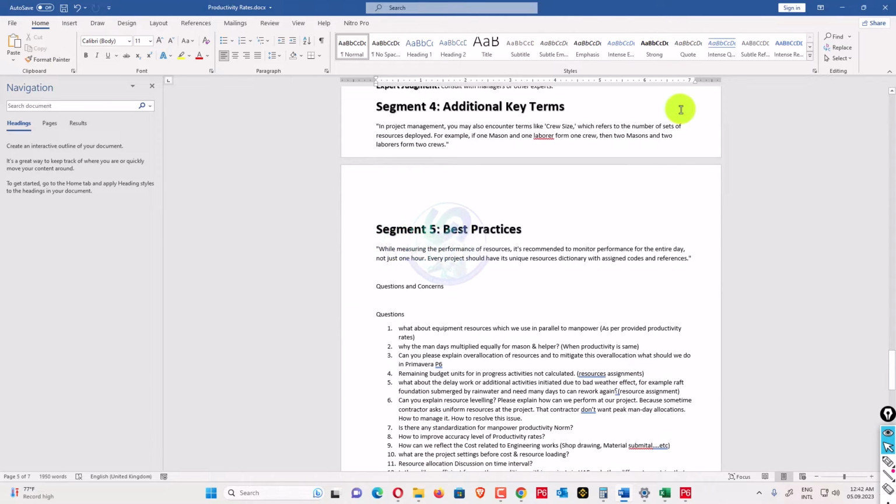I can consider that while measuring with your experience or historical data, there is another method. You can go in the field and observe the site data for 1 month or 2 months, or your planning manager, planning engineer, site planning engineer or supervisor will observe for the whole month what the productivity of this person is per day. He will just aggregate for weekly, monthly.